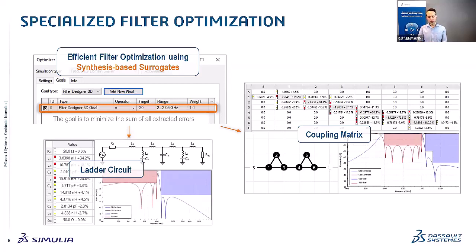We have even introduced or enhanced the parasitic extraction and parasitic and dispersive handling with some new technology in FT3D, which is worth mentioning because we have a patent pending on this. This is even more enhanced in version 2024, which I would recommend you try out for these low pass or high pass filters.